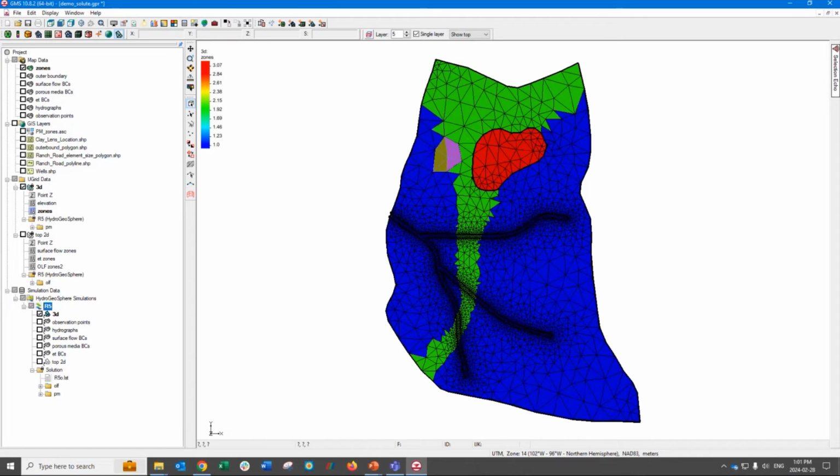Which of the HGS functions are not supported by GMS? That's a good question, and the list of features and functions not supported by GMS is going to be quite long. But in a nutshell, the GMS interface does not currently support any of the additional model domains beyond surface flow, subsurface flow, and the evapotranspiration domain. So that means no fractures, no channels, no pile drains or wells or other 1D hydraulic domains.